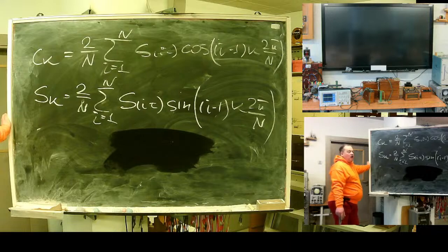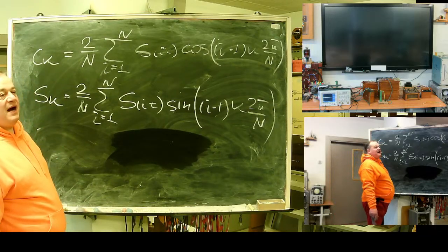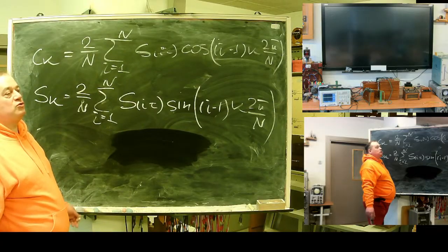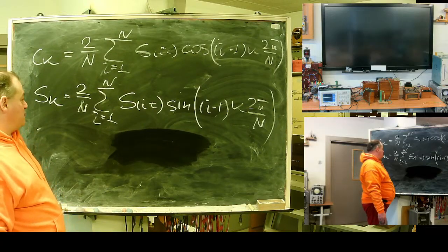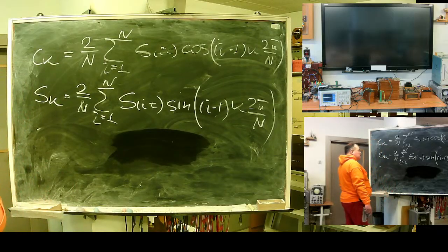Very typical for our business is, for example, 1 millisecond. This means 20 measurements per period. 20 isn't a power of 2. Because we don't need the full row, we are not obliged to use fast transforms, and we use the traditional discrete time Fourier transform.